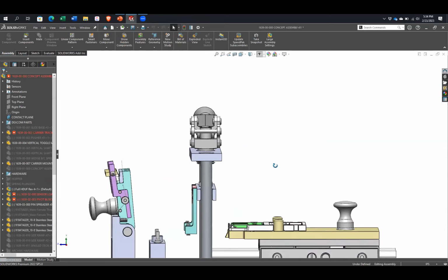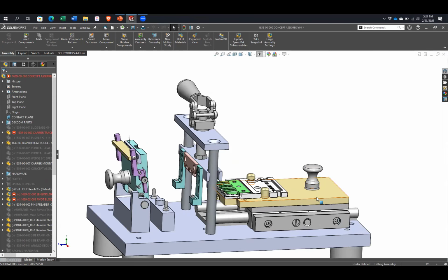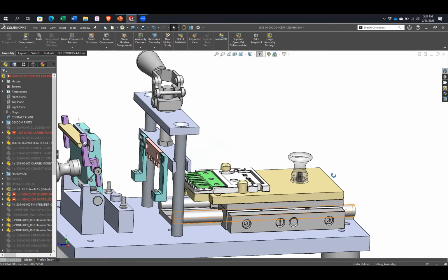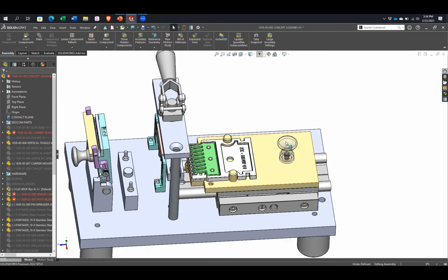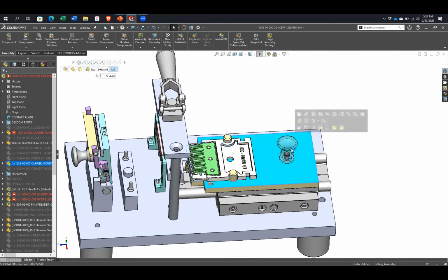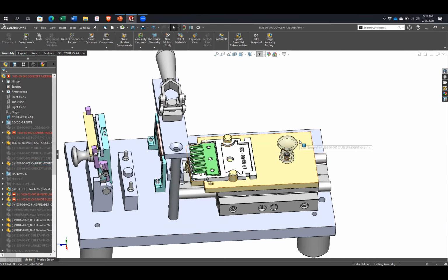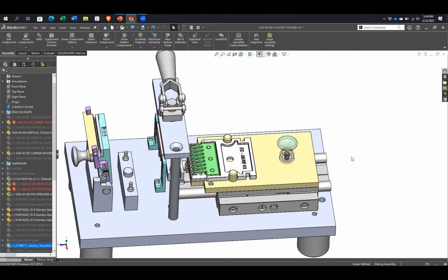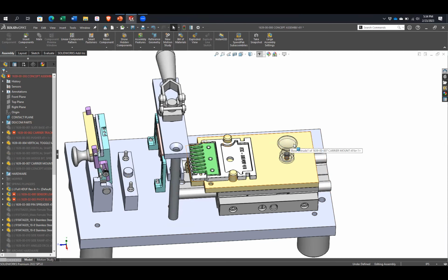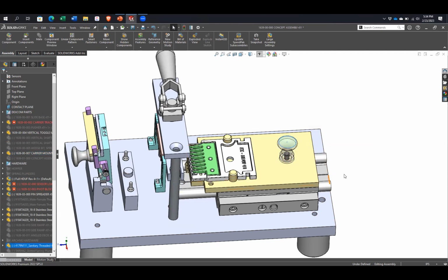The first thing I wanted to show: if something is transparent, let's make this knob transparent. Does anyone ever try to click on it and get really frustrated when you can't select the transparent model? Well, if you hit Shift, our old friend Shift again, that will actually not treat the model as transparent. Now when you hover over it, I can click it. I can click on given faces. Right now I can't select it. If I hit Shift, now I can select the face.